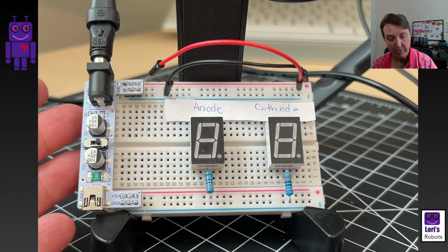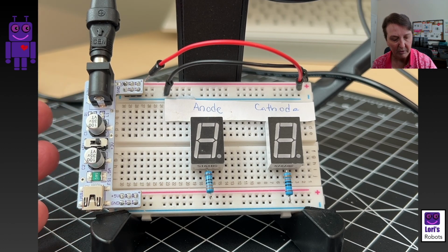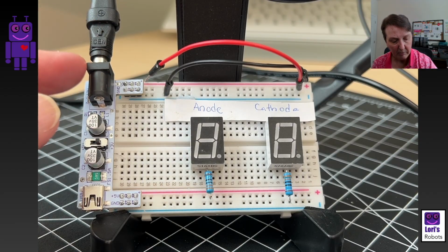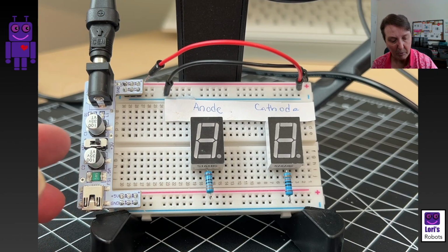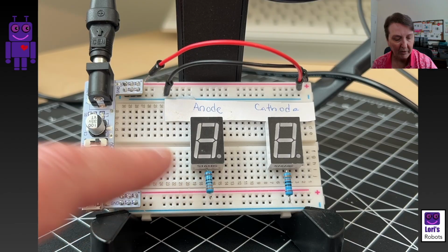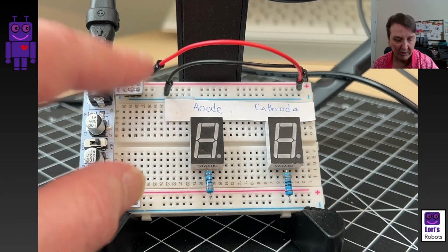And I'm using a breadboard power module to bring power and ground to the breadboard. I'm using one that can be powered this way with one of these jacks, and it also has a USB type jack that you could use to bring the power. And these breadboard modules allow you to put 5 volts or 3 volts on the rails. Some of them allow you to select what you're sending out, 3 or 5. And some of them it's one side or the other.